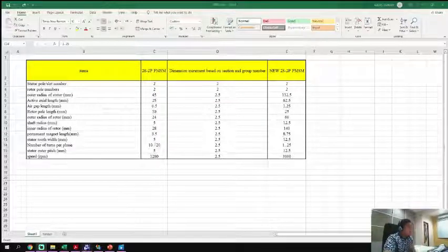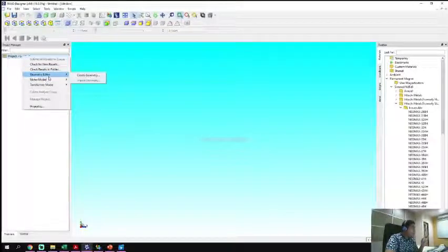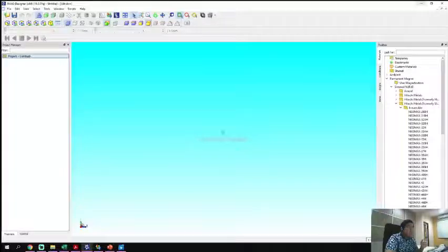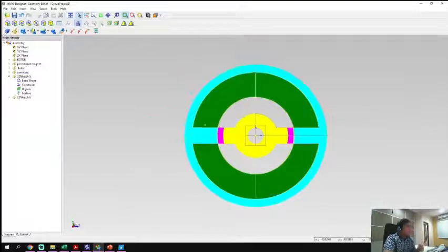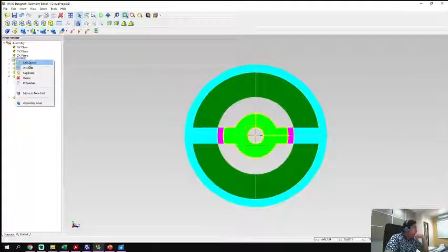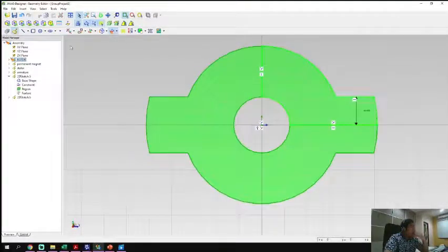Alright, now we go to part A. As you can see here, this is the blank JMAG. So we go to the project untitled, we go to the geometry editor, we create the geometry, and it will become like this. Then the next step is we need to create the 2D sketch. After we click it, we need to make a circle, and for example, we click here and just drag it out and we put in the data.